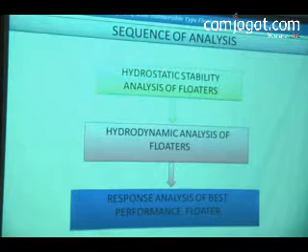Now we designed the semi-submersible for supporting the 5 megawatt wind turbine, and did hydrostability analysis for the floaters. We did hydrodynamic analysis of the floaters using WAMIT. Once we did these two cases for the different types of semi-submersibles, based on the RAOs we chose which is the best type of floater, and then we did the response analysis for different sea states.